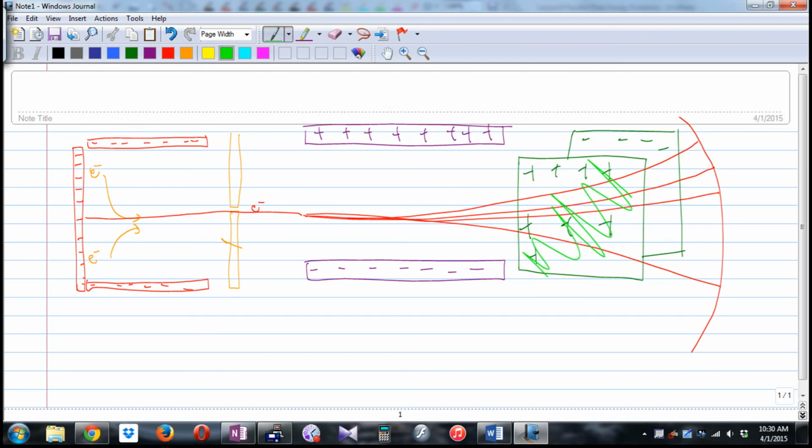That lets you deflect it either towards me or away from me. So now not only can I move an electron beam up and down, I can move it left and right. On that TV screen facing you, I can put an electron wherever you want it and make a little blip glow. And if I do several thousand electrons really fast, your brain will just automatically see a picture.